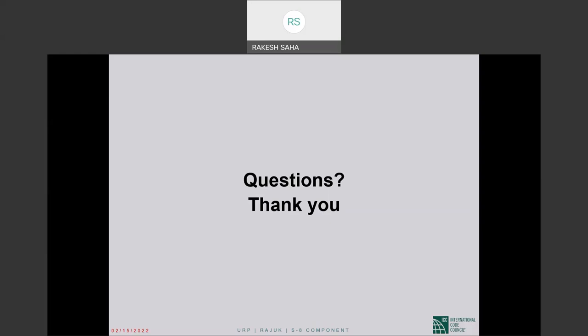I don't understand. Well, first of all, if you do modal response spectrum analysis, you will still have to do a drift check. The drift quantities will also be square root of the sum of the squares of modal drifts. Now, there is no scaling of drift. Only this is something important. I probably should have mentioned this. Only the force related quantities are scaled. The drifts are not scaled.